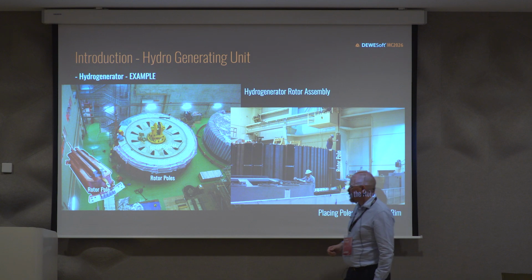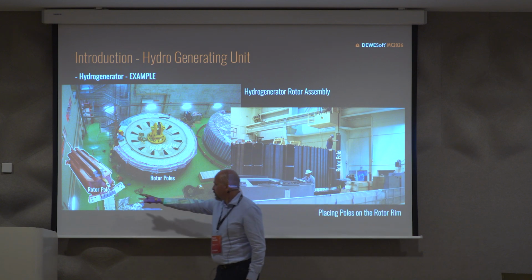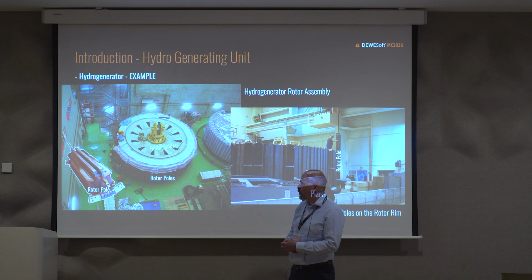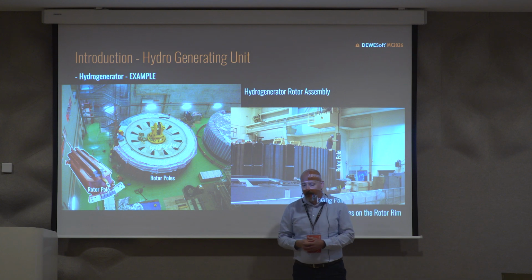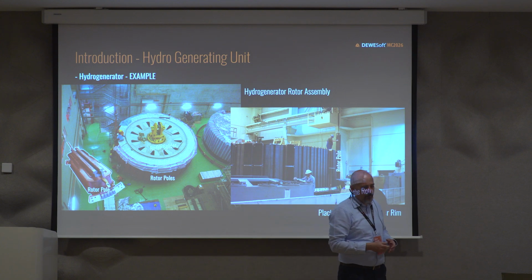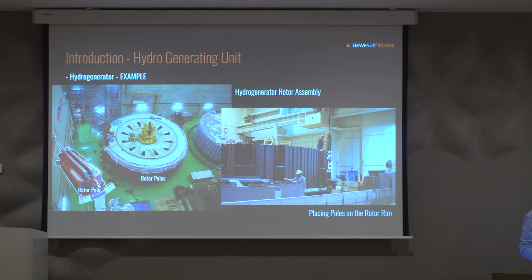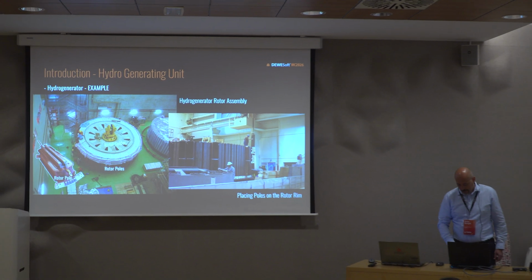So this is an example of the rotor pole. They're actually not screwed or fastened with bolts or similar to the rotor rim, but they're actually keyed to it. Otherwise, the centrifugal forces would be too large, and the thing would probably crack and fall apart. There is a reason why they are keyed to the rotor rim.